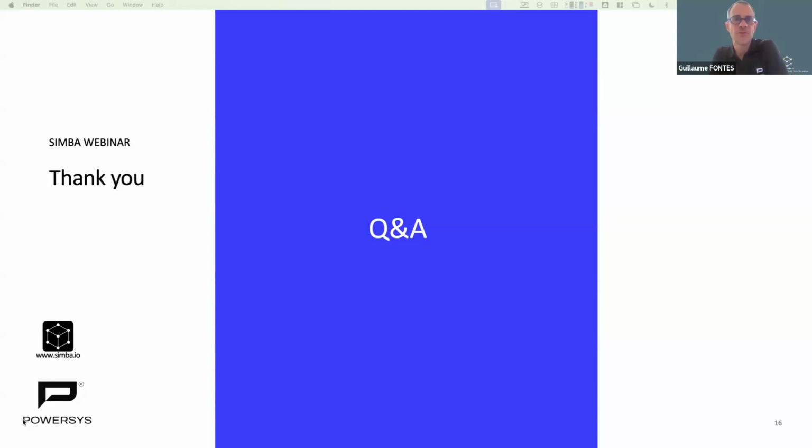Question from Pao, I think that will be for you, Guillaume. Exactly. So your question is, in low frequency applications where the switching frequency is below 16 kilohertz, does the DPWM, that's to say the discontinuous modulation, make a big difference in reducing losses? And what's the counterpart of these discontinuous modulation strategies? Well, I would say that the first answer is that we usually don't know before running a simulation and a study.